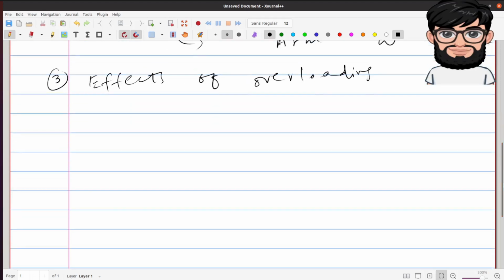So basically it's a long list. I'm just gonna say it out. Basically, if the plane is overloaded, you're gonna need a higher takeoff speed. So it's gonna become the takeoff speed at which the airplane is recommended to take off. The speed is gonna become higher, and the takeoff run is gonna become longer.